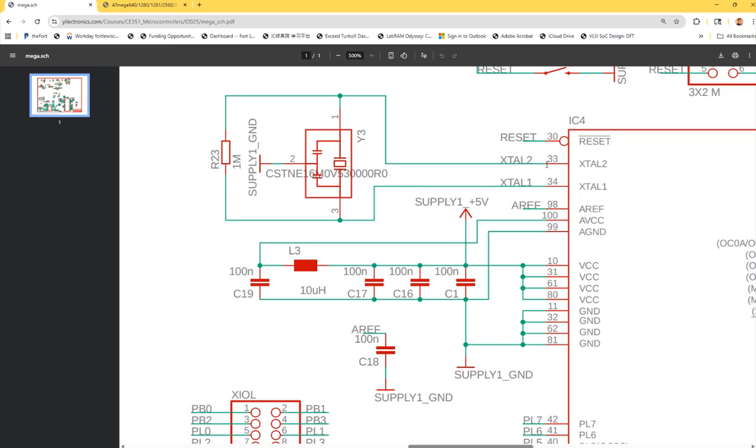And the clock, okay, so see the Arduino products, why they are not super popular in the industry. They're expensive, and they don't have a lot of peripherals on the chip, and they have external oscillators. So you can see a lot of the PIC ones, even though when you program it gives a lot of pain, but the PIC one I used is a 16-bit microcontroller with 2 to 3 UARTs on it. And it's only $1, and for this one $17, and even for the Arduino Uno, the very beginner's version, I think it only has 1 UART.